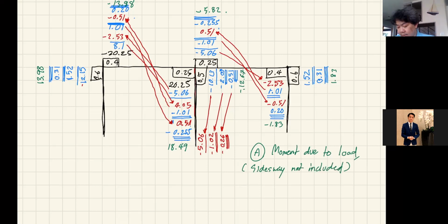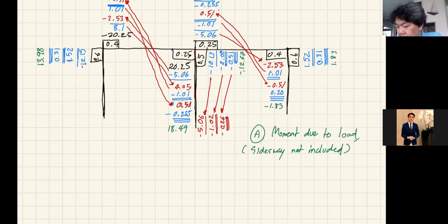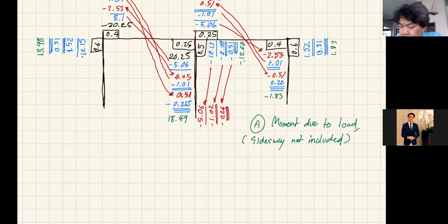So what we need to do now is break this down into the free body diagram and solve it for our base shear. It is the shear of the member, but when it is a shear at the support of your building, many times engineers call that the base shear, the shear at the base. So this free body diagram, be very mindful of your sign convention.